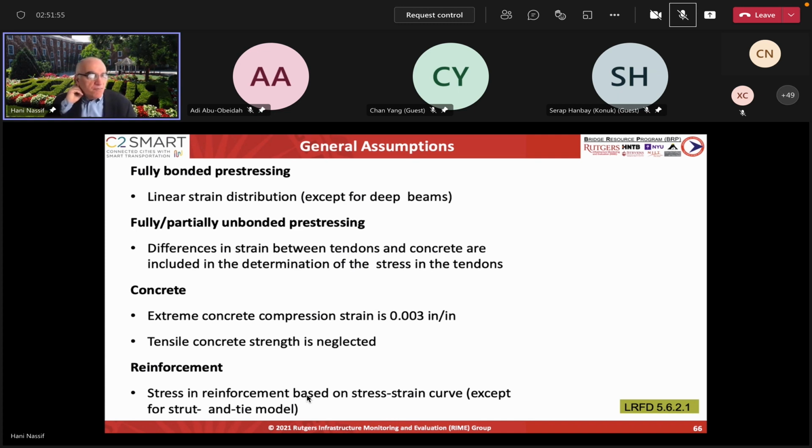And they used to talk about partial pre-stressing for unbonded, but I think AASHTO is moving away from partial pre-stressing. A lot of DOTs don't like it, and I understand that. The European approach is, so what if the pre-stressed concrete cracks? But here, especially in the northern tier, because of the use of de-icing salt, it's understandable that you want the girders to be preserved. You don't want them to be cracked.